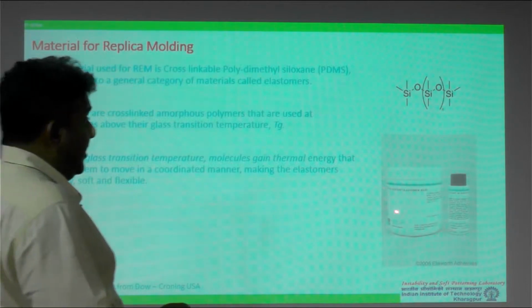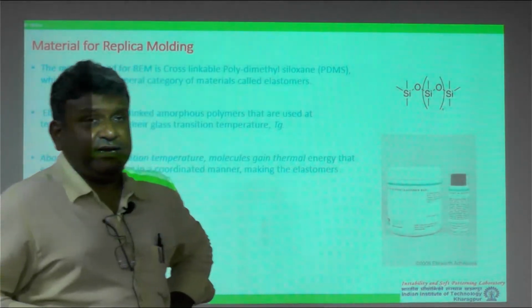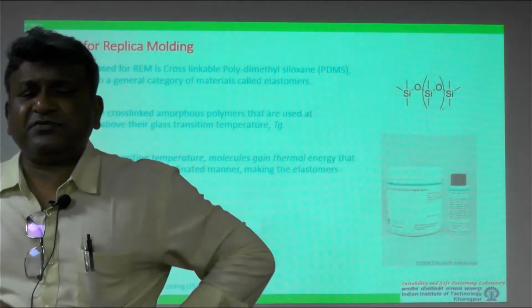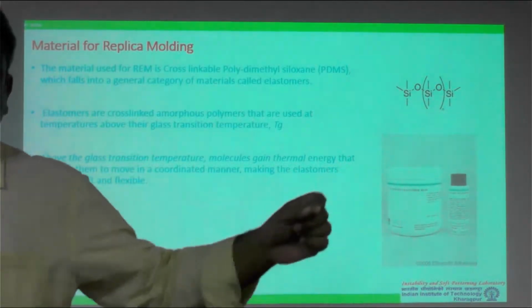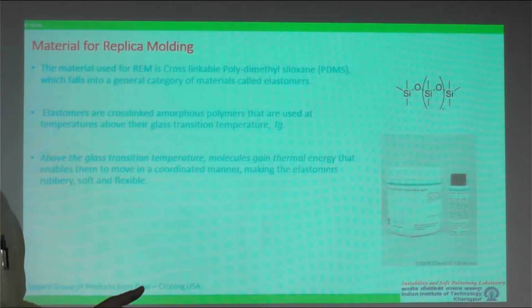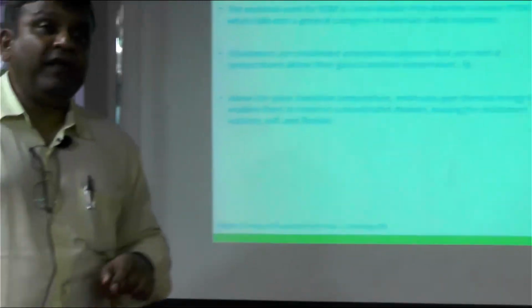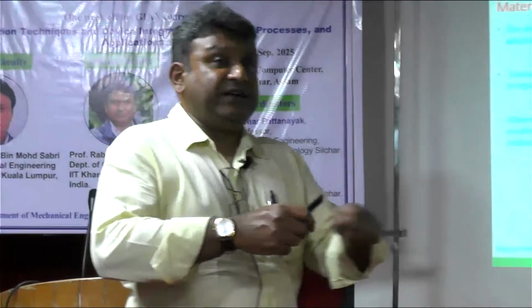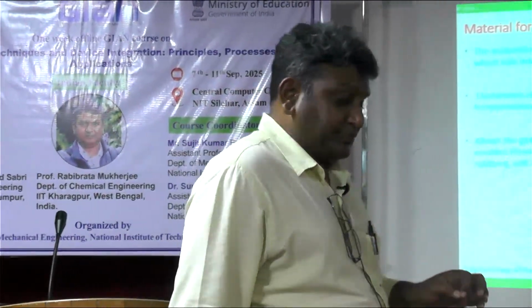The first part, part A, they call it the oligomer. What is an oligomer? It's a few chains. It's not a long-chain polymer, but a few chains of the monomer, right? And part B is the cross-linker. From the name itself, it's clear that if you add this and do something, and what that something is I will tell you, you basically create a cross-linked matrix.